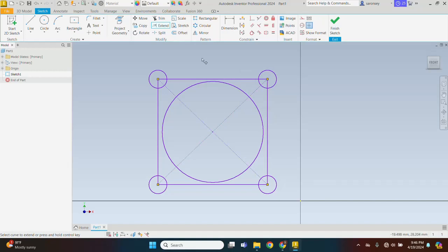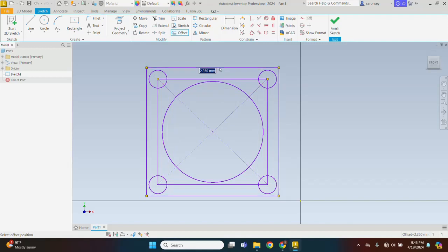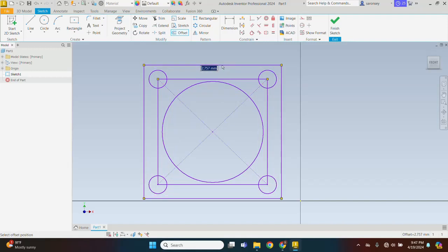All right. Now let's look at the offset command, which is one of my favorite commands. It allows you to draw a profile or repeat a profile either inward or outward. So let's see, we click on this profile and then we can drag in to any distance we want. So we can repeat that profile and specify the distance we want to move either inward or outward just to place. So here, let's assume I want to place it outward. I can just click and then I place another profile which is either bigger or smaller than the initial profile.